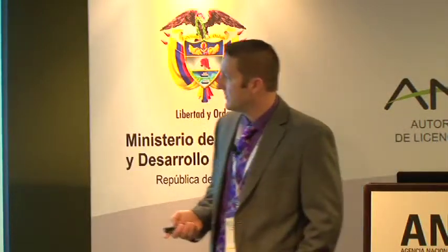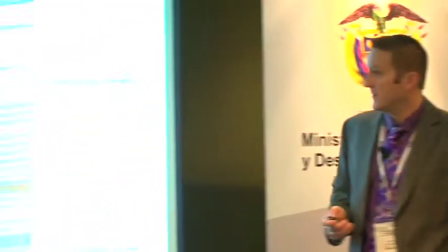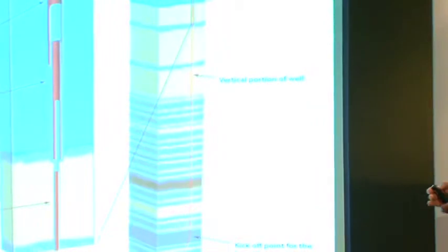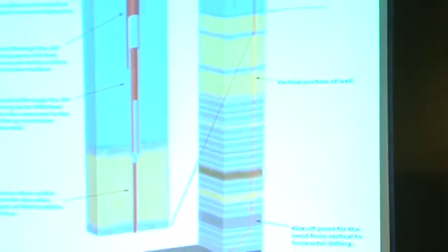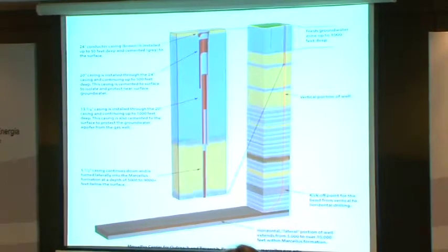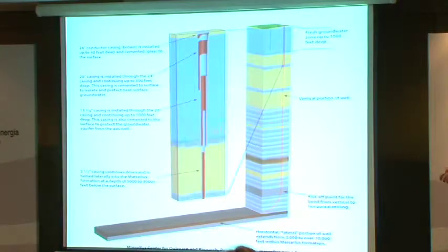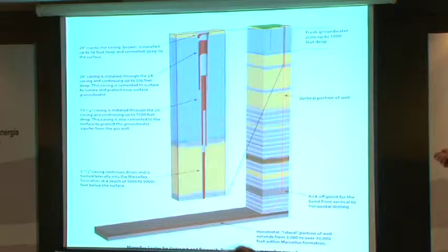Really the most critical part of the operation is to make sure that the wells are being drilled properly. And we've seen really a complete revamp of our oil and gas regulations in Pennsylvania that you'll hear more about this afternoon. But really where the rubber meets the road here is to make sure that the wells are constructed properly in the upper 1 to maybe 3,000 feet, or roughly 300 to 1,000 meters, to make sure that the deeper part of the shale is hydraulically isolated from the near surface water resources, both groundwater and surface water, so that there is no potential for vertical communication there.